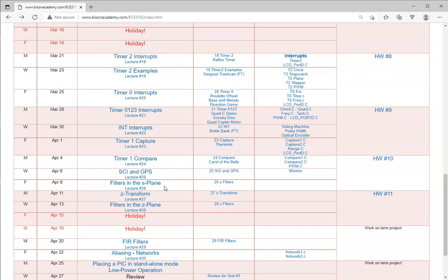So then rather than having to write the code that says, did you hit the button? Did you hit the button? Did you hit the button? I only call the subroutine when I need to, when I hit the button. It really simplifies some things, but it's a really strange concept, really powerful, really useful, and likewise, a third of the semester is spent on interrupts.